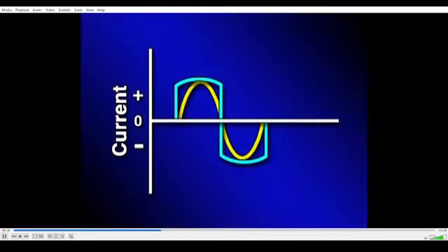Conventional square wave technology was introduced in the 1970s. Conventional square wave revolutionized gas tungsten arc welding because it digitally processed the AC cycle to eliminate the gradual transitions between positive and negative half cycles. The end result is a smoother arc because the change from positive to negative is instantaneous, and the arc is more efficient because it spends more time near the peak cleaning and penetration portions of the cycle.